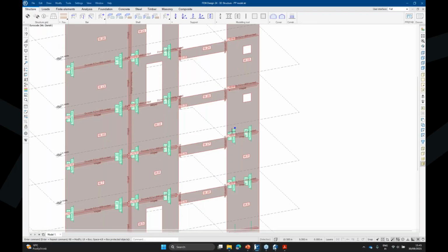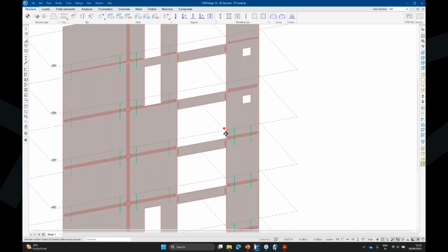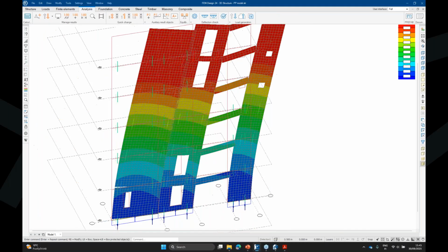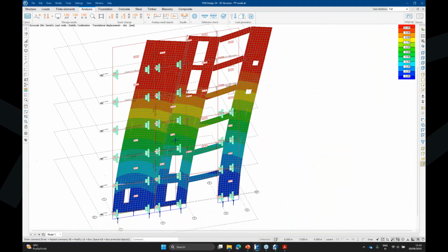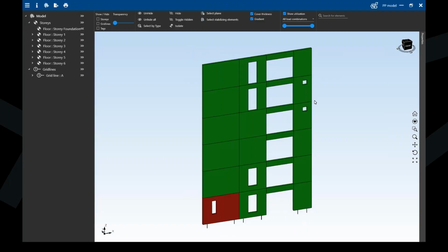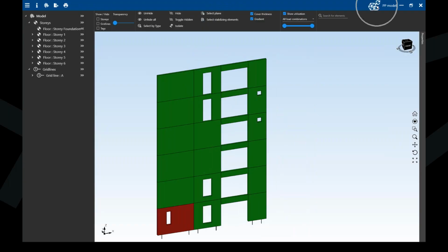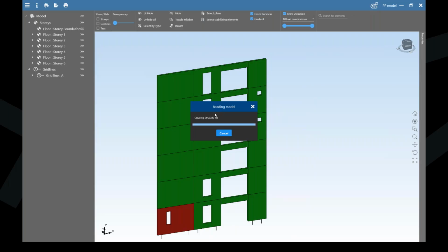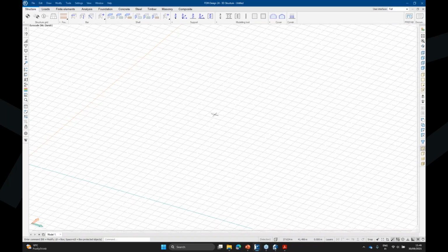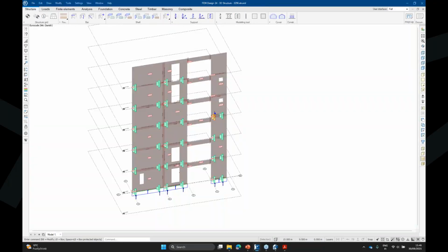So first of all, we have a FEM-Design model here. It's a non-linear model, but it can be a linear model as well. And then we get our deformation, so we get uplifts and tensile forces. Prefab can be started with this button on the top right-hand side of FEM-Design. It will start Prefab, and if the model is not showing here, you can click this button to update your model. So it will read the FEM-Design model back. If you have multiple models open, it will ask which one you want to use for plastic optimization.